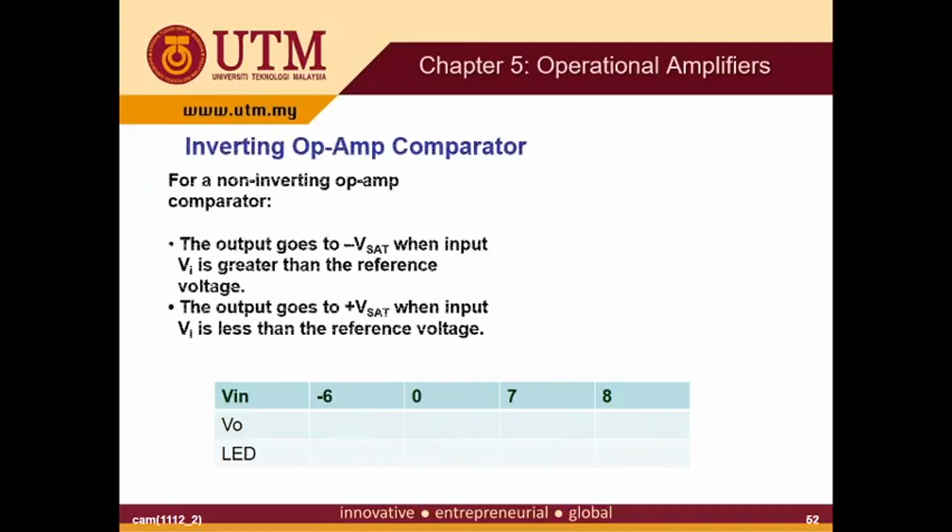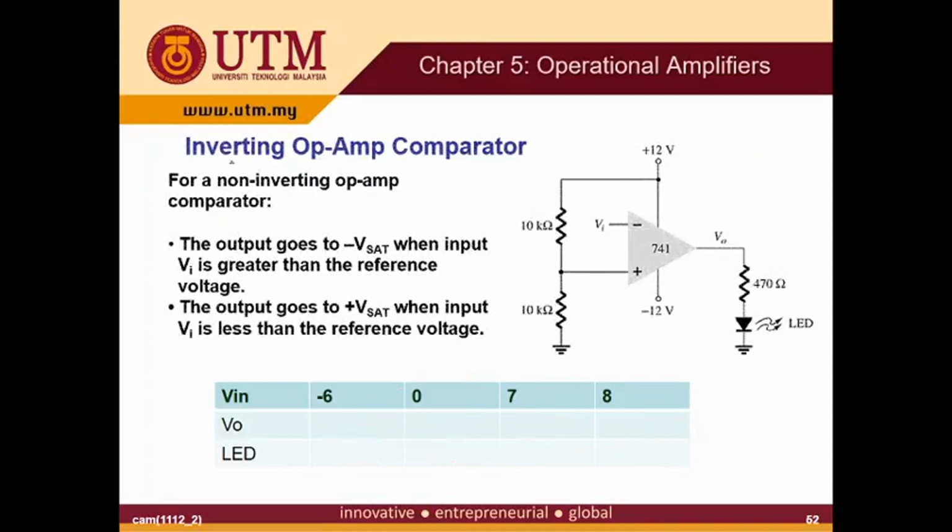So you can also have an inverting op-amp. For the inverting op-amp, the input is connected to the V minus, and the reference is your V plus. This is the same setup, where your V reference is plus 6 volt. So we do the same analysis.